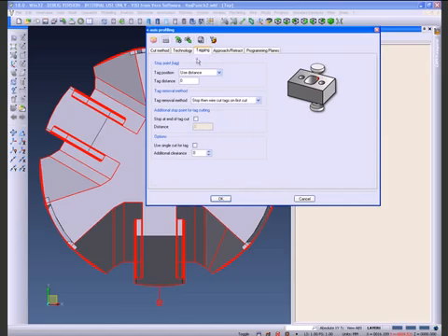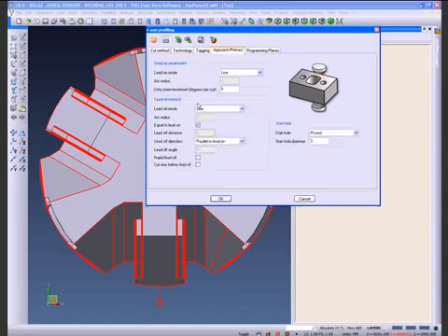What we're looking to do now is go into the tagging option and change the tagging distance that we're going to add in here of 3 mm, and we're also going to add in a length of this particular tag and also lead-ons to approach the part from the tag and to the tag.